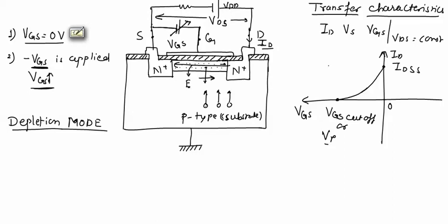Now remember again the MOS capacitor. In the MOS capacitor, when we applied a positive gate to source voltage or positive gate voltage, then up to a certain value of positive voltage, the charge carrier concentration in the channel will be same. And for large positive voltage, a large number of electrons from p type substrate will be attracted in the channel, and these electrons will form inversion layer.